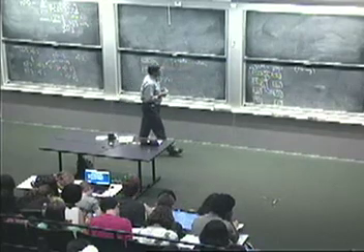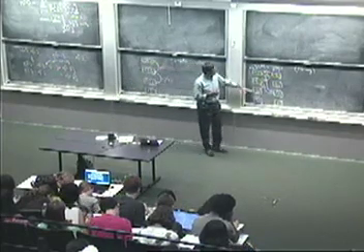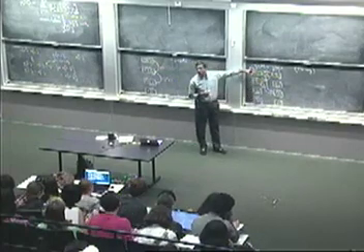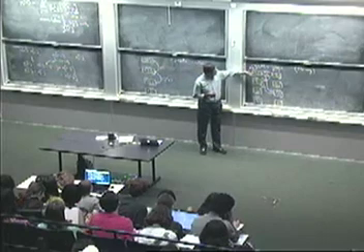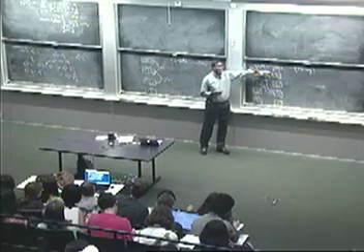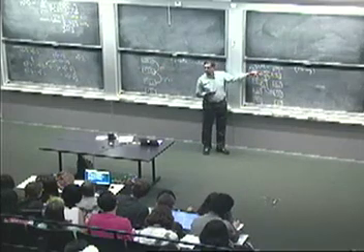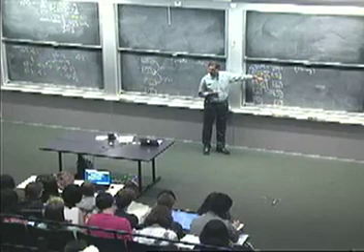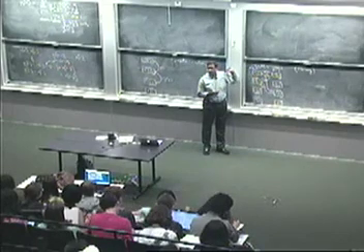Now, there's a simplification we'll make in drawing this. Because I've arranged the states in natural binary counting order, 0,0, 0,1, 1,0, and 1,1, it's always the case that the upper arrow that emanates from a state corresponds to an input of 0, and the lower arrow corresponds to an input of 1. Okay?